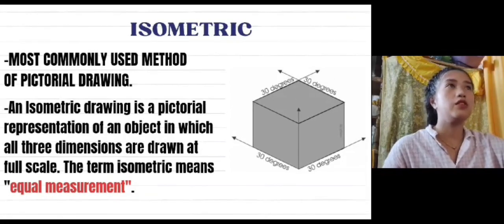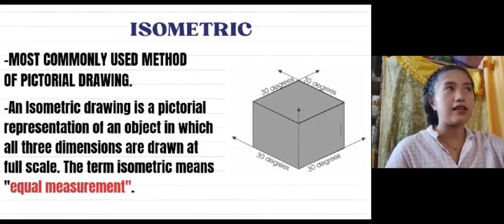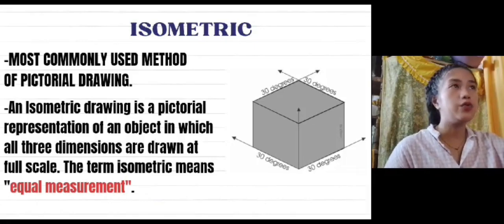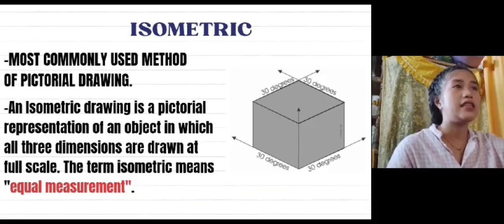Isometric drawings are built on three lines called isometric axes. One is drawn vertically and the other two with a 30-degree set square on either side of it. An isometric drawing is a way of presenting a design in three dimensions. They can be completed using the 30/60 set square or freehand.